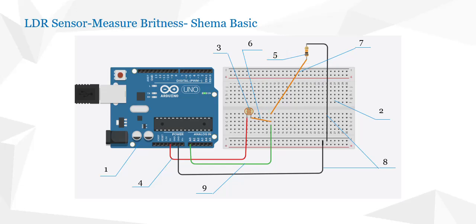You can see number 5. The other end of that resistor is connected to ground. You can see it as the black wire. The long line on the breadboard marked with minus below is at the same potential. 2 black wires are connected this way.